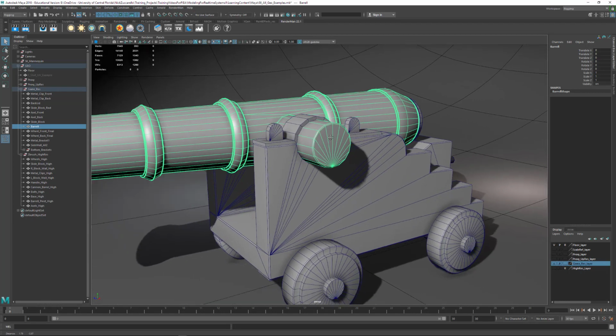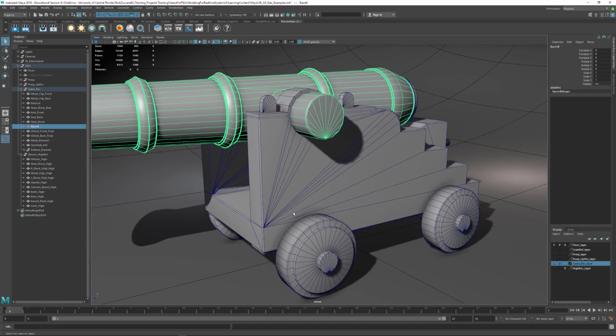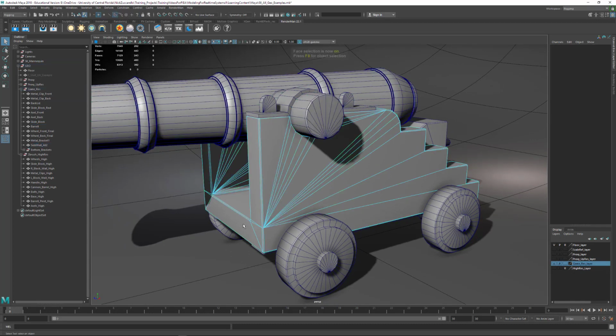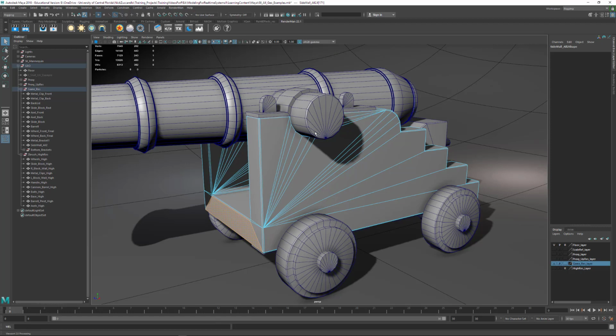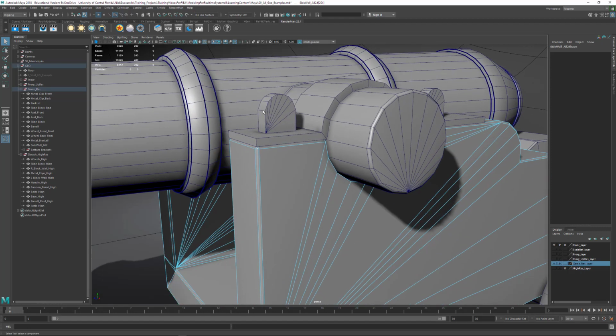And on the ends of these caps, I went through, and if you select, let's say, a polygon like this, we can shift right click and say triangulate faces, and it triangulated these big faces that we had here pretty easily for me. These parts here were a little bit chunky.